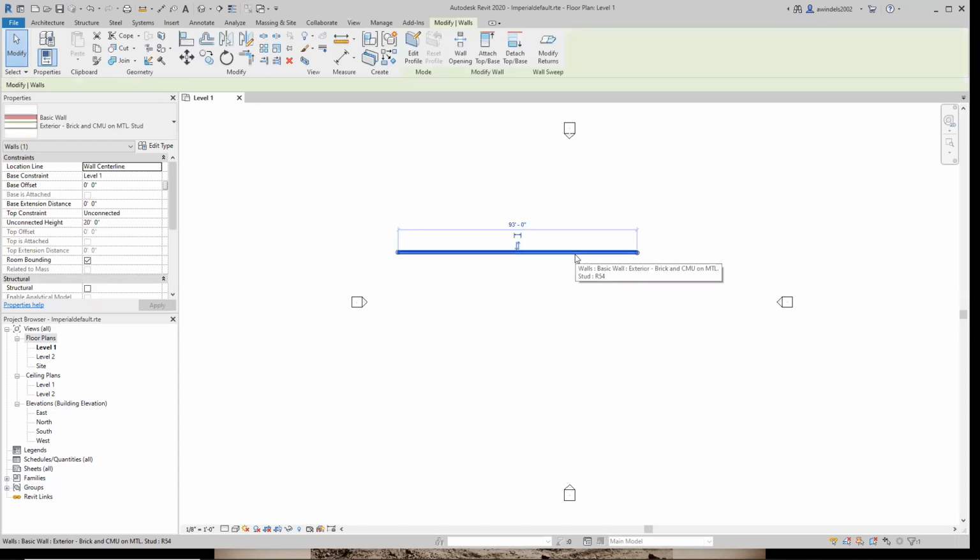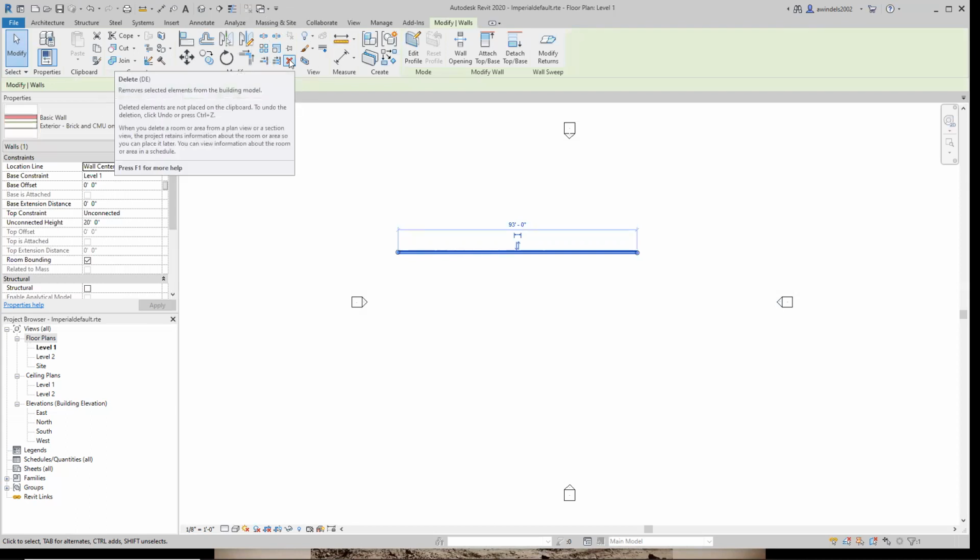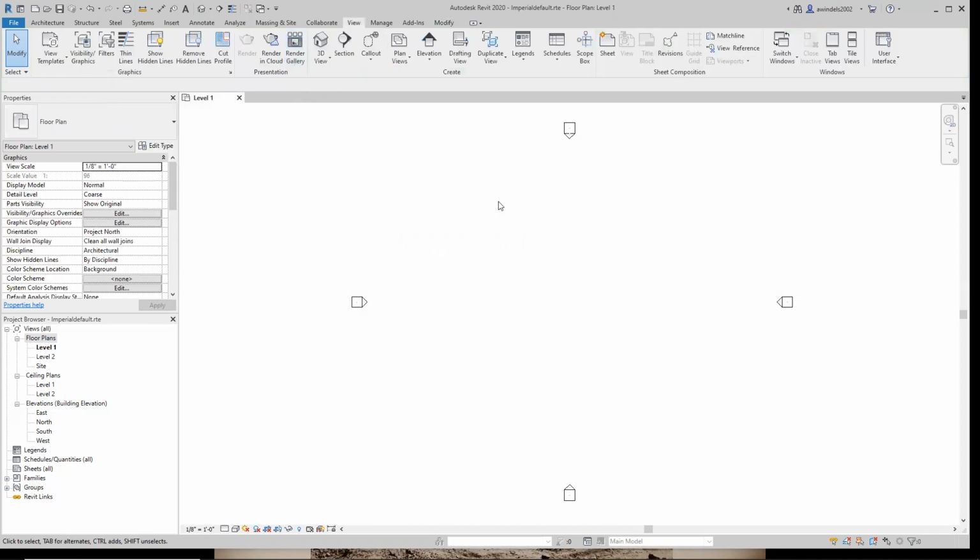Let's delete this wall, select it, and hit delete, quite simply, or you could hit this button, delete, or DE. You notice when I hover on commands, you can see the little acronym next to the bold delete. DE is the same alias command you can type on your keyboard to get that as well. So you're going to find yourself memorizing some of those if you want to be faster at this. But knowing where they are in the ribbon is more helpful to start.